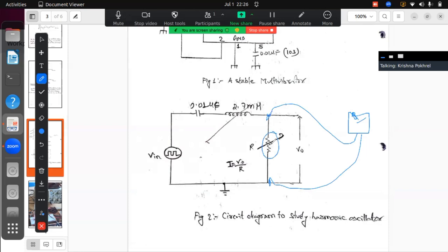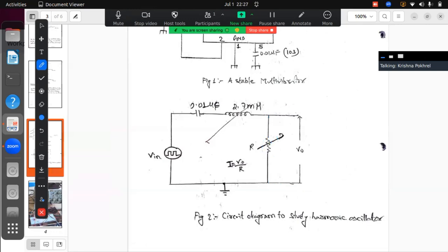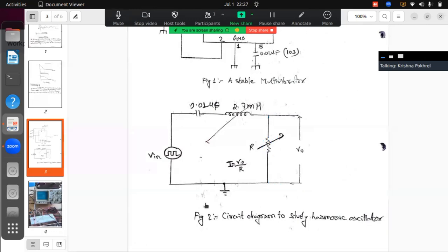Sometimes, if you take out a 200 ohm resistance, you will see a critical damping. That is not good according to our theory. But according to this resistance box, the resistance is infinity. It's also an overdamping or critical damping condition. But there may be some error, and there may be confusion among the students. So you can measure this thing. I'm sharing my knowledge with you all, what problem I faced in the practical lab. So I want to go further.